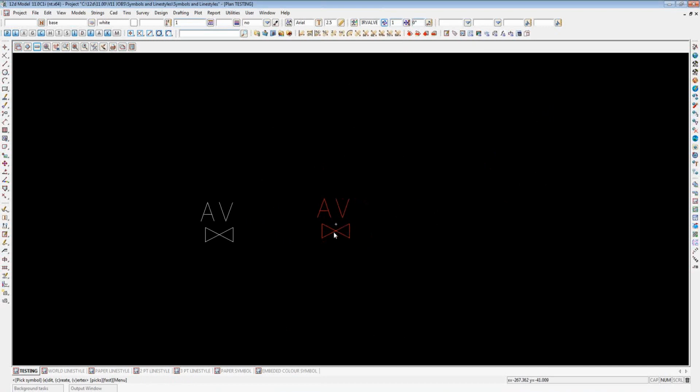The other thing you'll notice, and we get questions about this quite often, is you see a little point in the center of my symbol. People don't want to see this point, so the way to avoid the point showing up in the middle of the symbol is, when you create any symbols, change the line style to 0, which means don't display the line style. So when I create a point, I get my symbol color there with no point.